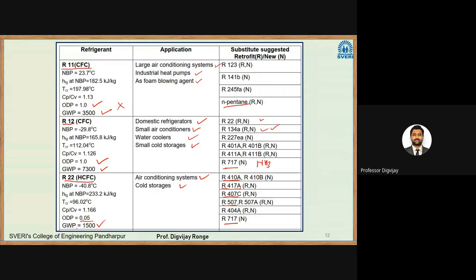that gas is very toxic. That gas is nothing but ammonia. If you eat that food, chances are that food poisoning will happen, and you may be hospitalized. So that ammonia gas is very toxic to human beings. Where plants use ammonia as a refrigerant, sensors are used to detect leaks. Whenever leakage happens, the sensor gives the information to the operator, and then he can detect where the leakage is taking place. But apart from that toxicity, ammonia is a very good refrigerant. It has zero ozone depletion potential and very low global warming potential.